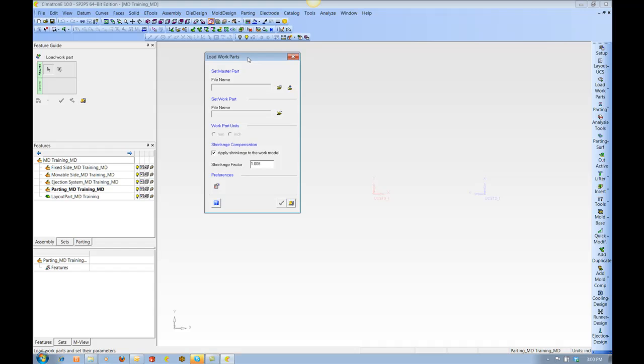Okay, because we haven't done quick split yet, we're going to set the master part, which is the one we had open a few minutes ago, here. Had we taken the option of doing the parting wizard earlier, when I said we had a decision to make, we could have opened up the parting wizard and done the quick split there, in which case we'd be picking this one if we already have the part quick split.